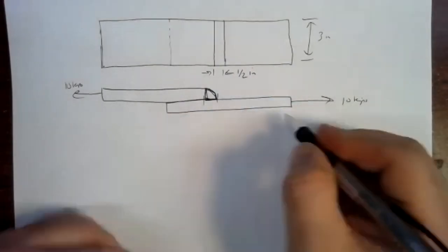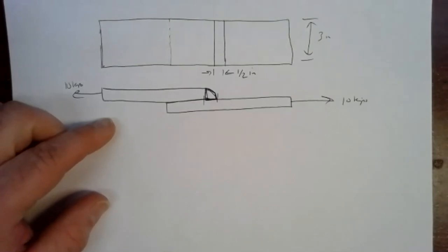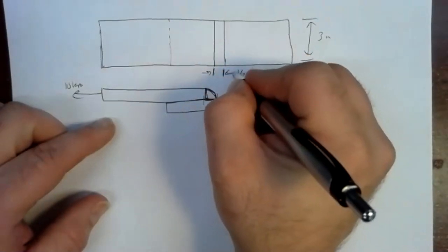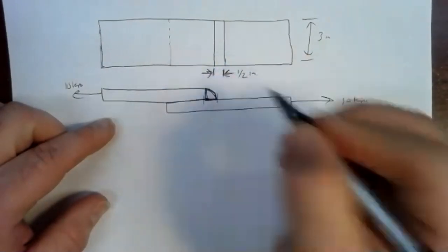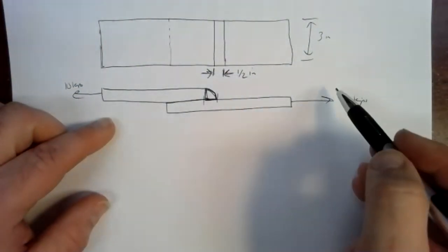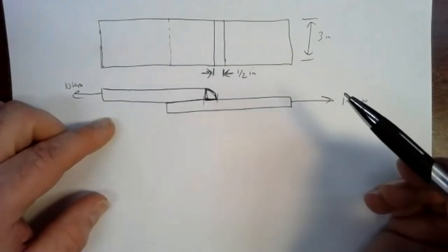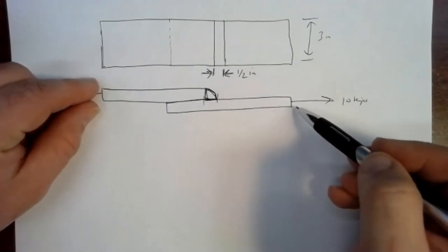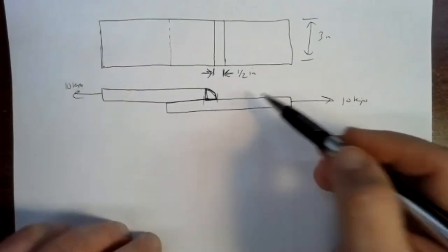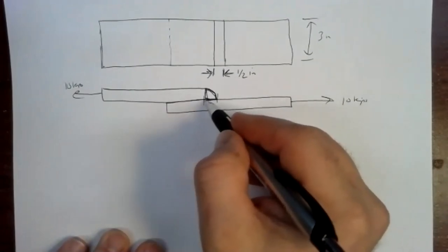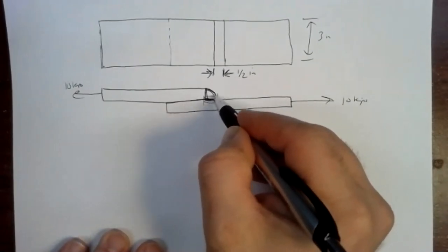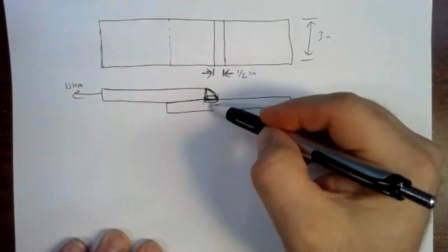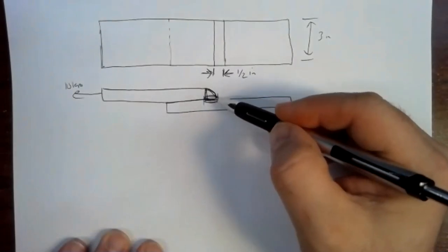So if we look at the contact area, unfortunately, one of the things we don't do in the AMP program, but that I've done in other welding classes, is that we do a weld and then break it. You do a weld and then you clamp onto both ends with a load frame. You pull on it till it breaks, and you see where it breaks and how it breaks. If we pulled on this thing, it could likely break in this area. That's one of the areas where we haven't gotten sufficient penetration with the weld. The weld isn't made with high enough quality.